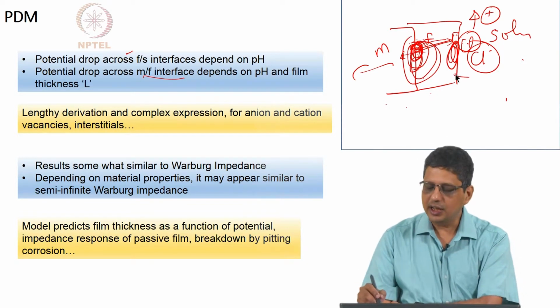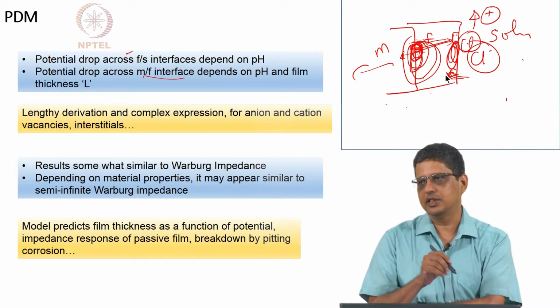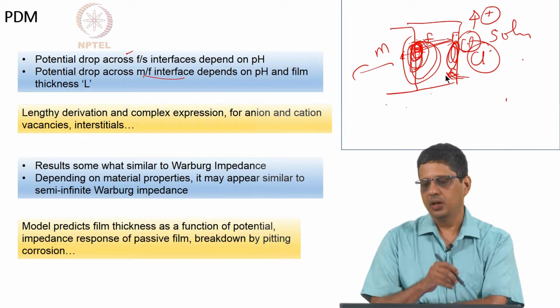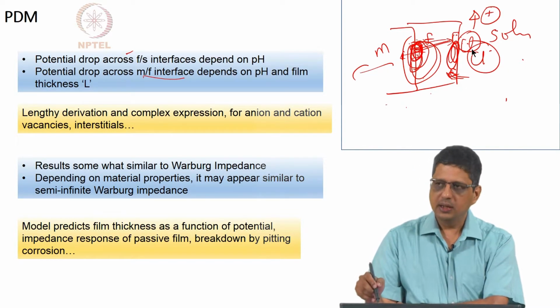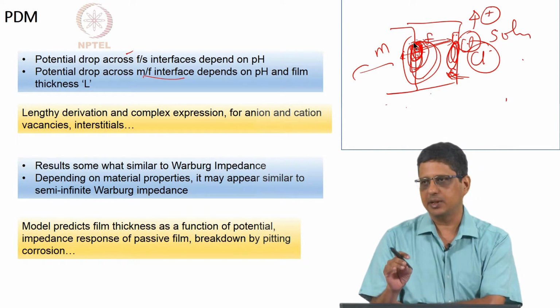It is not that the dissolution occurs more rapidly on the film surface, the film solution interface. That also explains why it takes some time, because the vacancies have to accumulate to some level. So, it explains why that incubation time is seen experimentally.